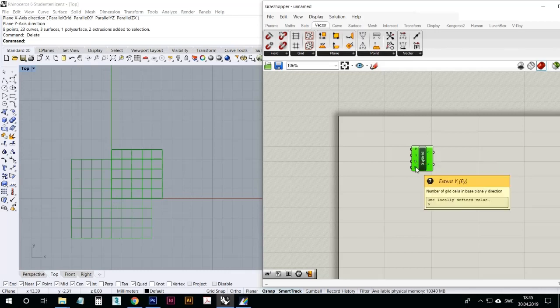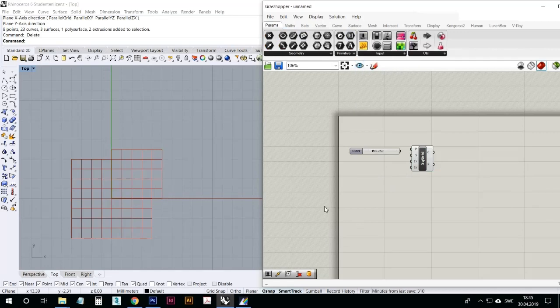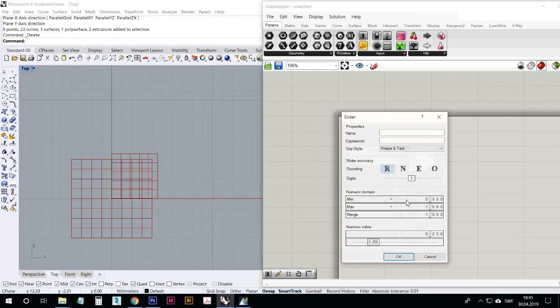So what we can do now is to take out some sliders that you find here, right? I took it from the lower left now because it suggested it. So one of them can be the size, maybe, like that. And another one has to actually start with 1, because you cannot have less than one cell in each row, right? Otherwise the component would turn red. So I'll take, for example, from 1 to 10, or you can put whatever you want to and go to integers, because it's going to be integers anyway.